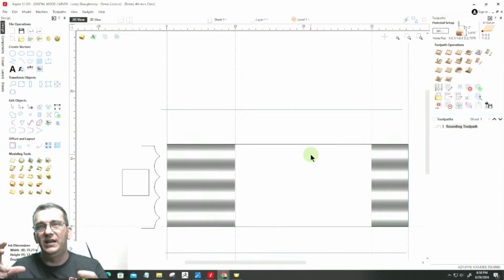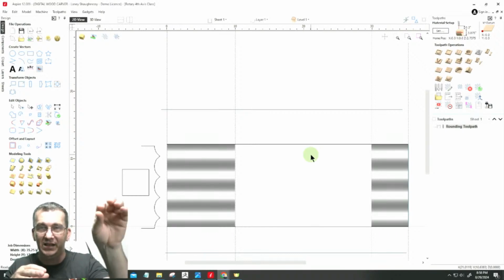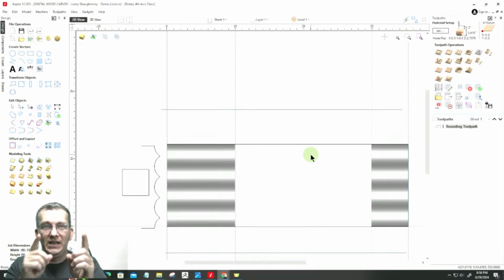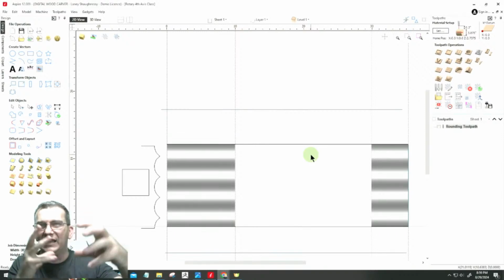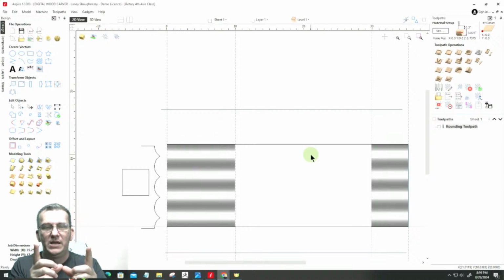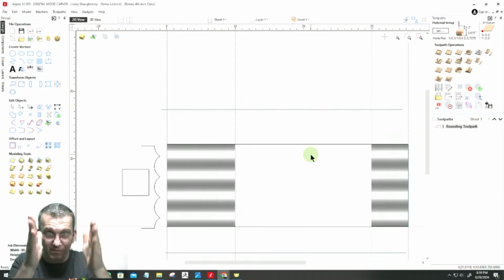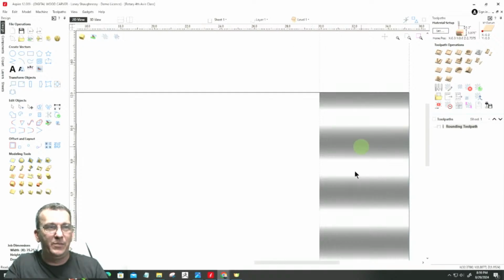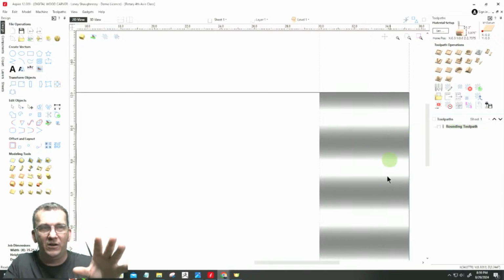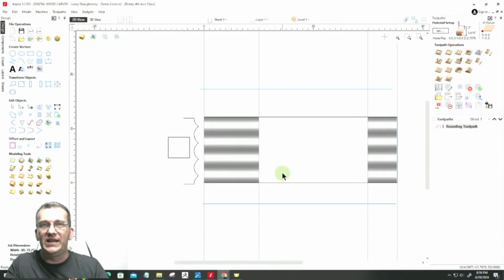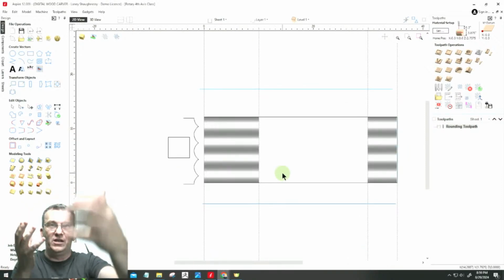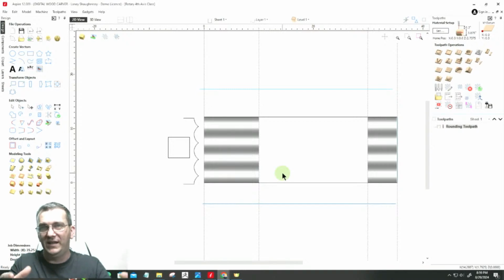Then they did the same leg, but in the portions where they could use a specific bit to cut that same design, they did so, and only the portion where they needed the Vectric software for the model part, like a set of leaves or grapes, was modeled. They drew a vector for that end part, created a 3D rough, a 3D finish, and a model for the toolpath. But for the rest of the table leg, I could use a specific bit to do the twist and wrap around and the cove and all that stuff.